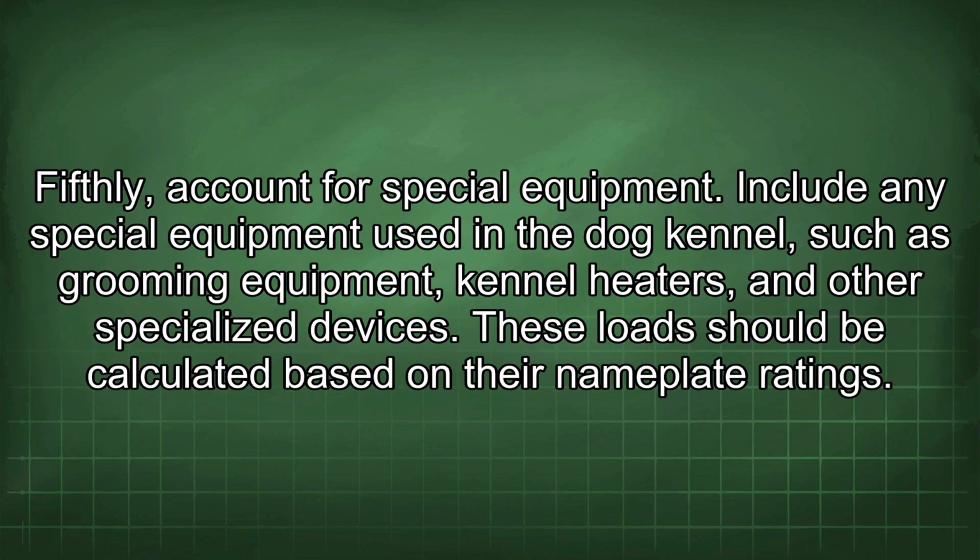Fifthly, account for special equipment. Include any special equipment used in the dog kennel, such as grooming equipment, kennel heaters, and other specialized devices. These loads should be calculated based on the nameplate ratings.